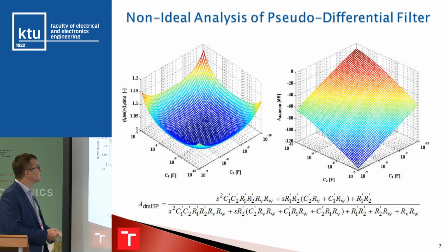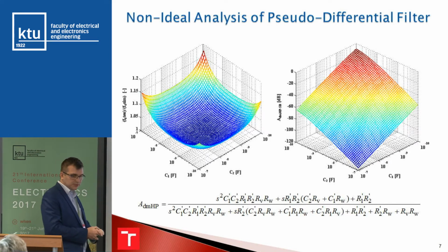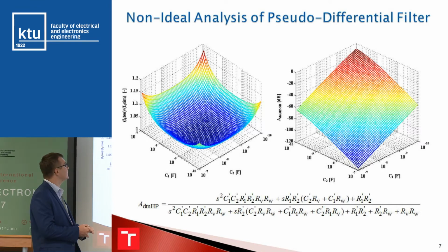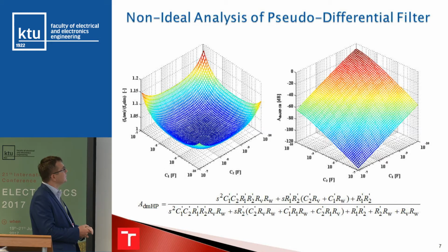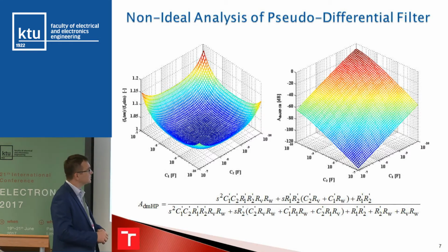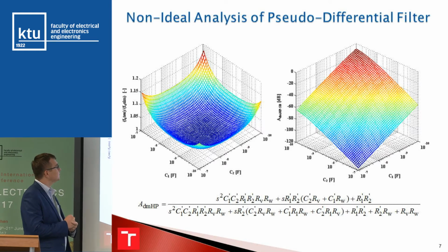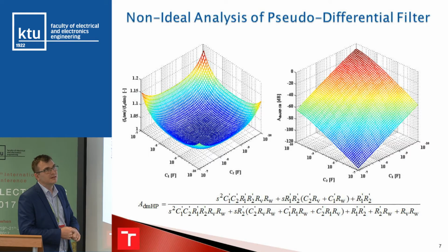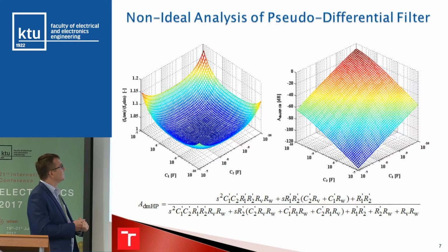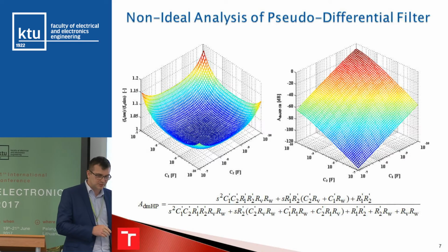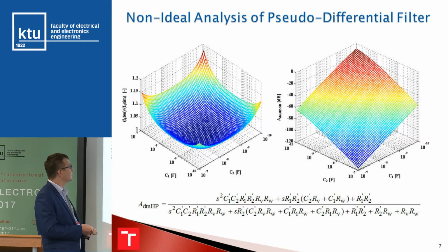Above that, what we deal with is the analysis of parasitic properties of the active elements that we use, because they are not ideal. In this case, we show the influence of parasitic impedances of the input and output terminals, and here we can see that you cannot stick to the ideal mathematical equation and count the values of passive elements and so on. You just select a few of them. There should always be something behind.